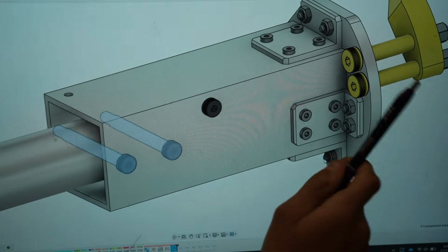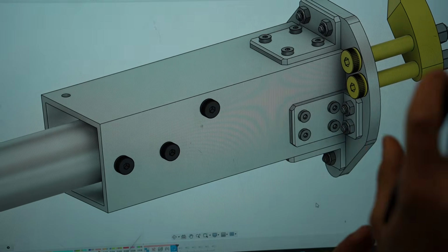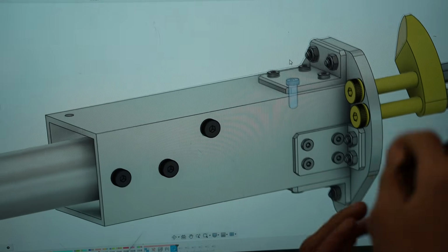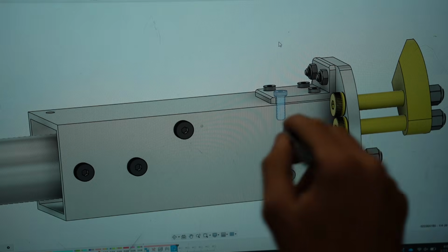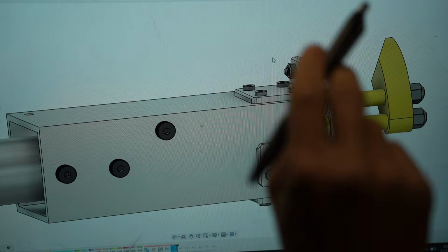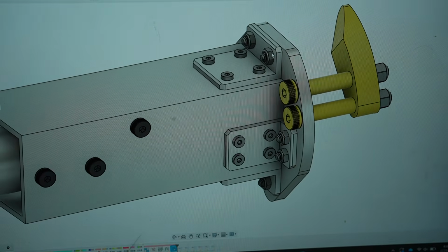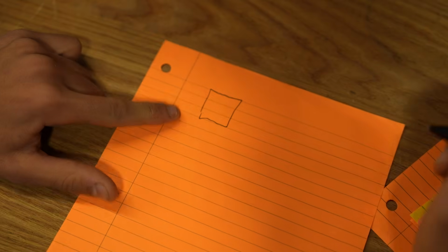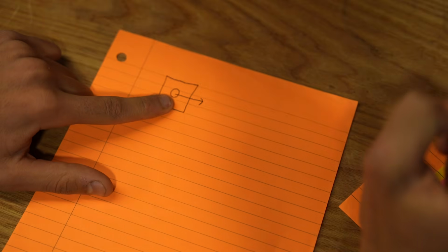So we use pins here that we're going to go into the math of, and then we're not going to go into the math of these brackets. We did very rough bounding calculations on the cross-sectional area of these screws, and their ability to resist the torsion and pull out here, in particular using the bearing strength of the aluminum. Let's go to that real quick. Very simply, you have a hunk of metal, you put a bolt in it, you apply a load to that bolt.